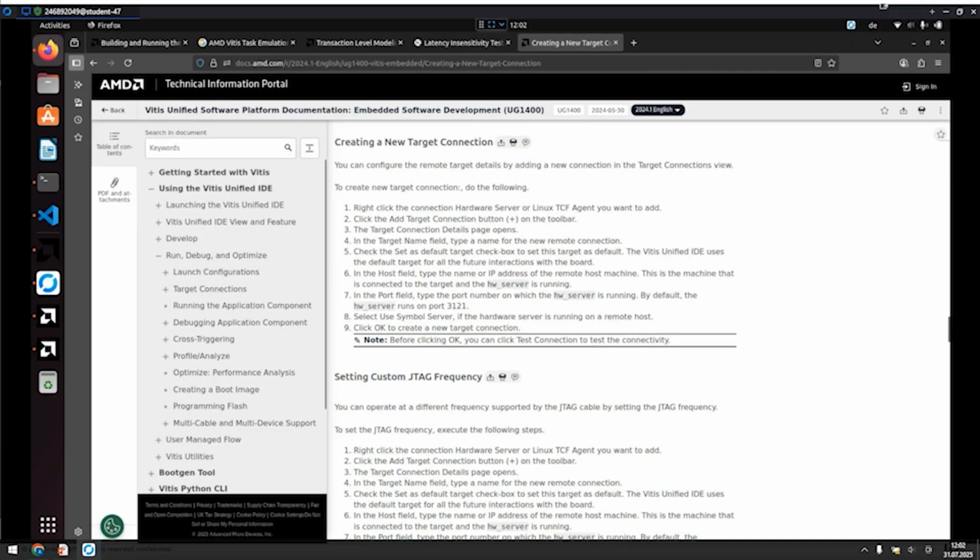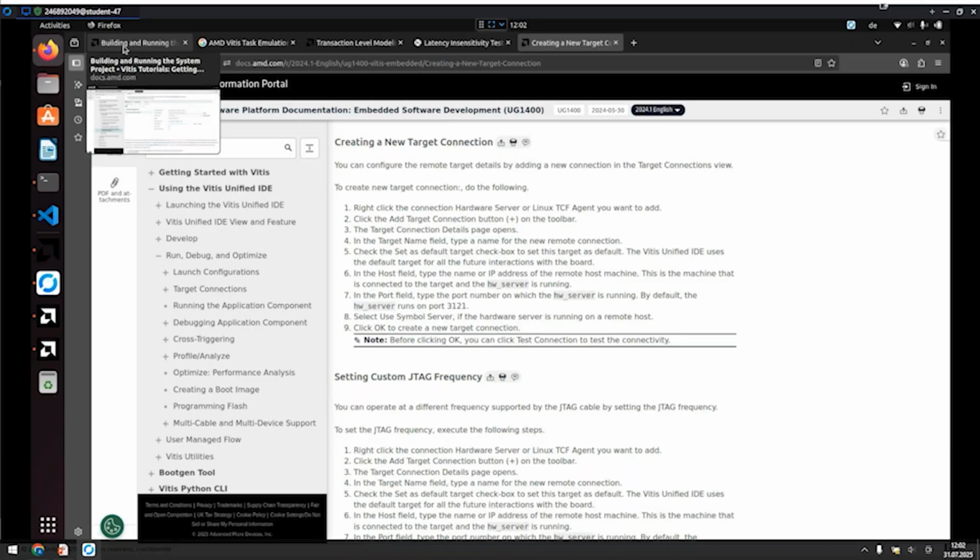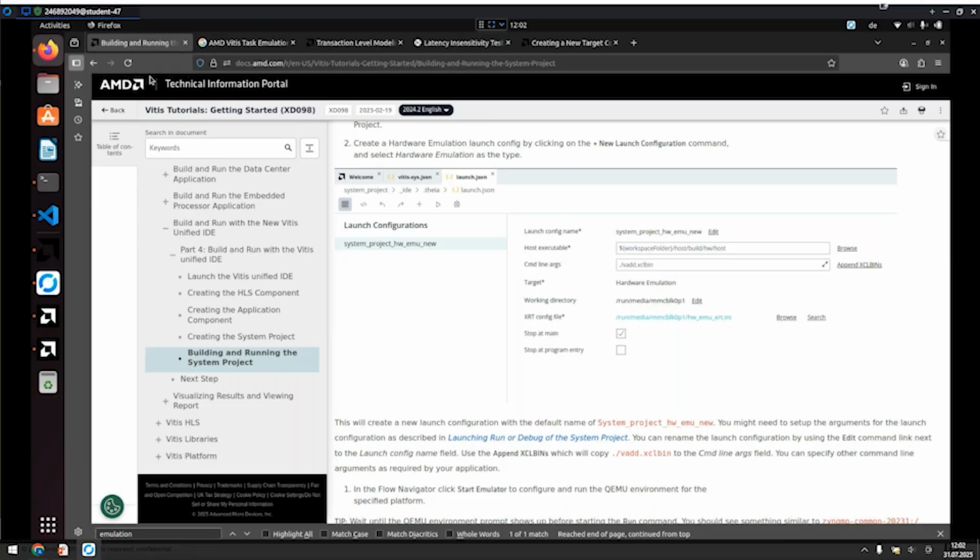But I will definitely put it back into the mails that we have in there. When you look into the QEMU command line arguments, you will find them in the Xilinx documentation, and this is where these things are set up, and it's really a lot of things. So it's always a good starting point to get this auto-generated, because the compiler toolchain creates it. And then you have all of these special links, like how you join up the network interfaces into these emulation processes and so on. If you get mixed up there, you can have dangling processes, and that can be very interesting. So I know it's there, but I don't have it at hand right now.